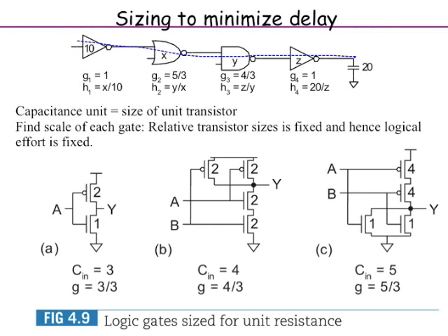Okay, and now let us look at the logical effort. For the inverter it is 1, G equals 1. Logical effort of NOR 2 is 5 by 3. Why? Because you take any NOR 2, 5, and compare it to an inverter, 3. 5 by 3 is the logical effort of NOR 2. Logical effort of NAND 2 is 4 by 3. Why? Because this NAND 2 is 2 plus 2, 4, divided by 3.